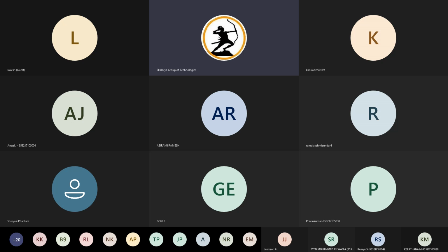So these are the memory types in the 8051. One is the on-chip memory and the second is the off-chip memory. In the on-chip memory we store register-related data, interrupt service routine, stack data and frequently accessed data. If we need to store large data, we go for the external off-chip memory.